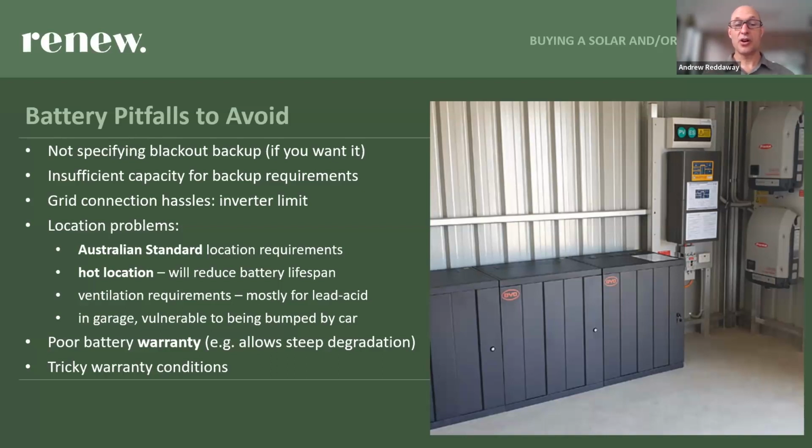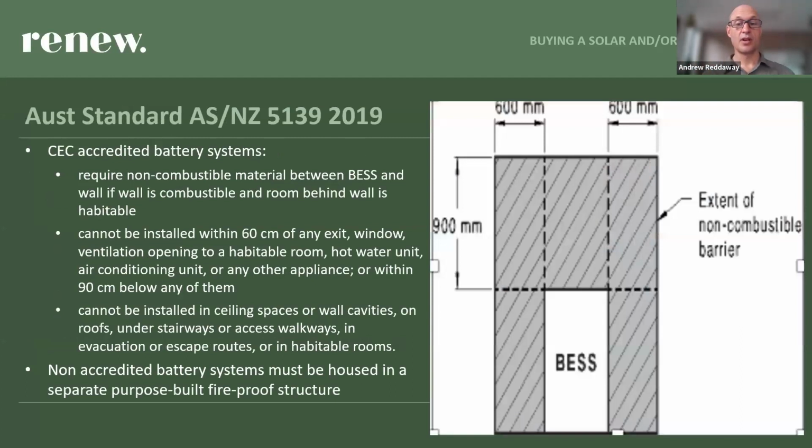You don't want the battery to get too hot. Actually, if the battery gets below 10 degrees or so, then it may have limited power levels as well. If it's in a garage, if it's possible that a car or a van might bump it, then you may need to have a bollard installed to protect the battery. Watch out for battery warranties and warranty conditions because it's a bit of an investment. Like typical battery investment, yeah, $10,000-15,000. So it's worth checking out what you're actually getting.